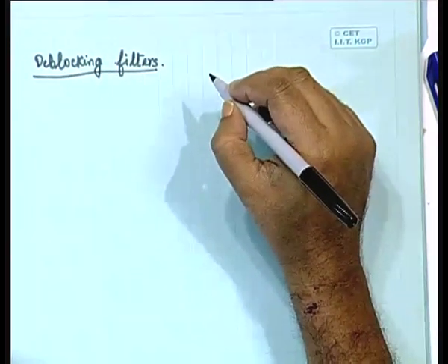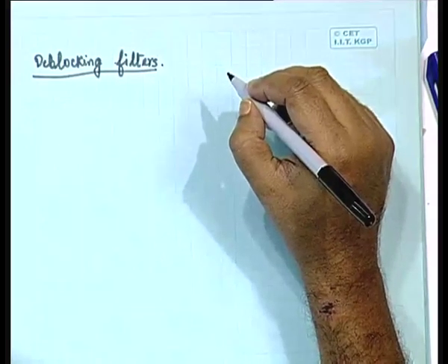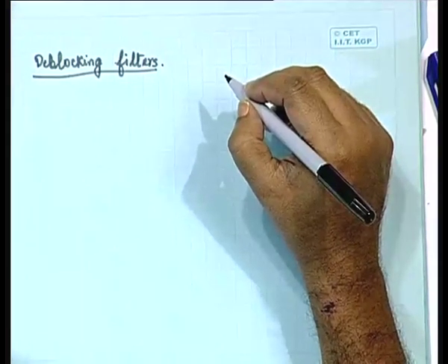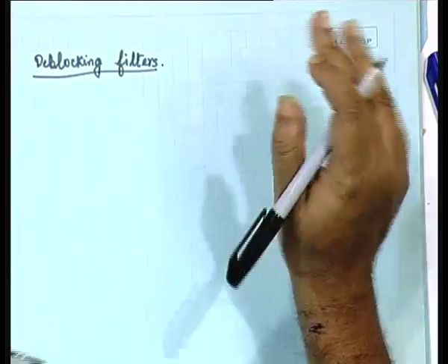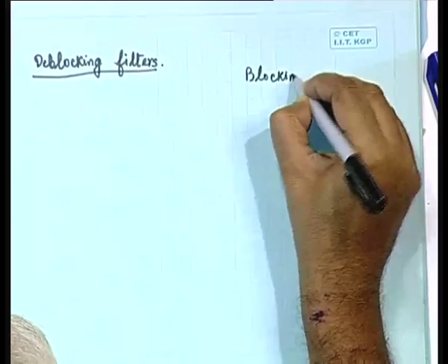You see, one of the major shortcomings of H.264, or any block based coding in fact, is that whenever you are partitioning the frame into a number of non overlapping blocks, you have got block boundaries, and across the block boundaries you are having some form of discontinuous information, which is present in the form of what is referred to as the blocking artifacts.